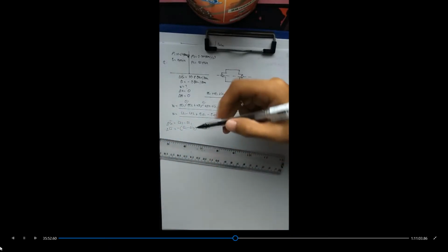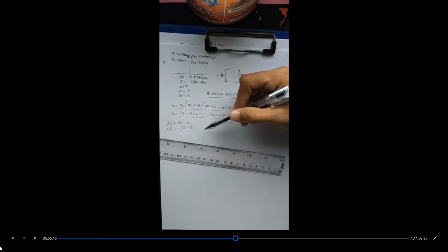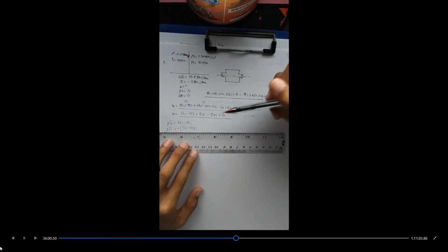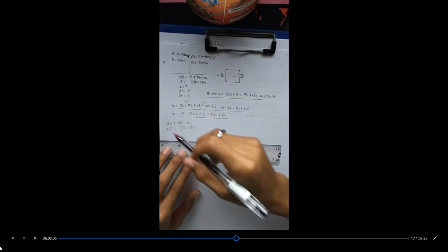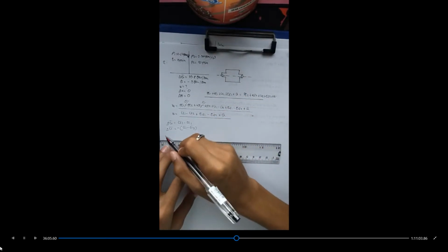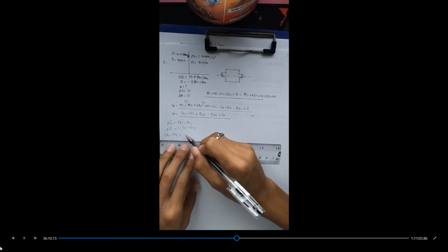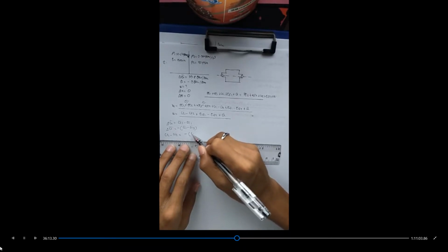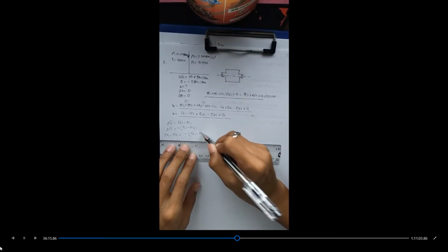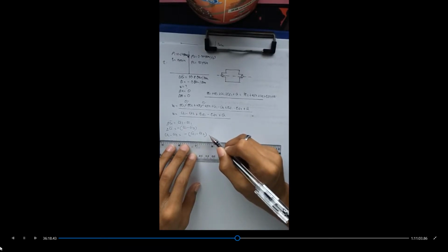Since this is specific, in order to make this into internal energy, not specific internal energy, we need to multiply the change in specific internal energy by our mass. That's why we need to solve for mass first. Since we don't have a value for our mass yet, let me just show the general equation. U1 minus U2 is equivalent to negative (u1 minus u2) times mass.